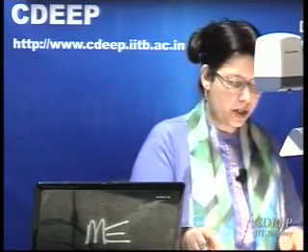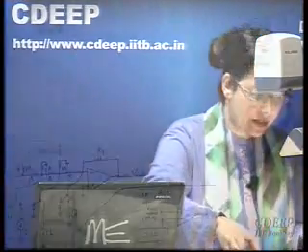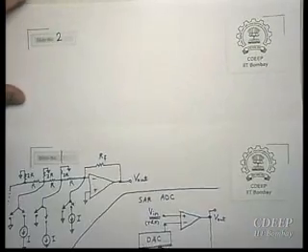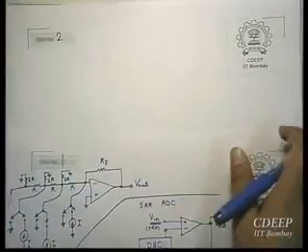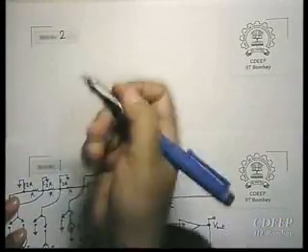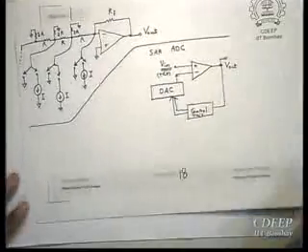The same capacitors used for charge distribution and charge scaling are also used to sample the input signal. So it saves the number of capacitors, and you will have a more cost-effective version of this SAR ADC. We will have the same thing, only now we will sample the signal also on the same capacitor array. That is the only difference. So now, this is the sample, in fact the comparator.